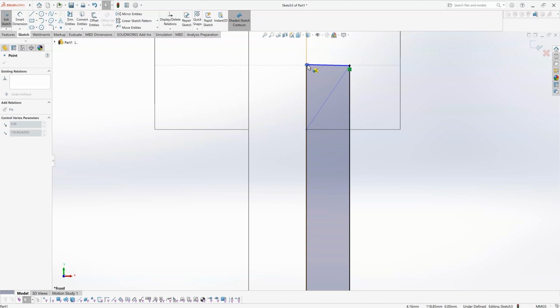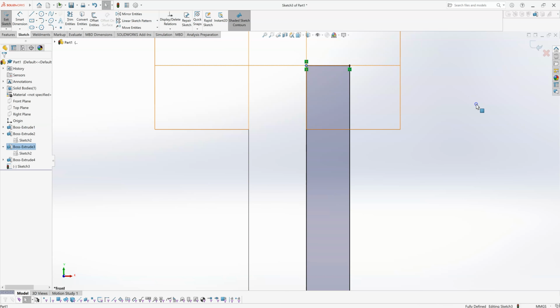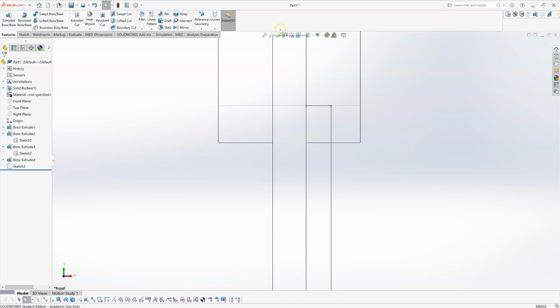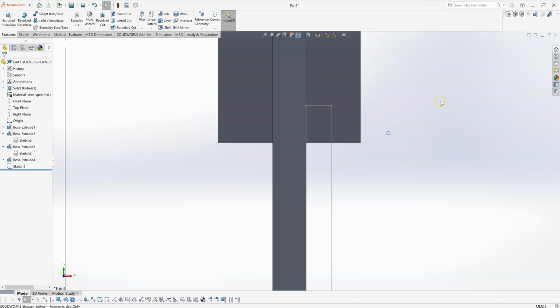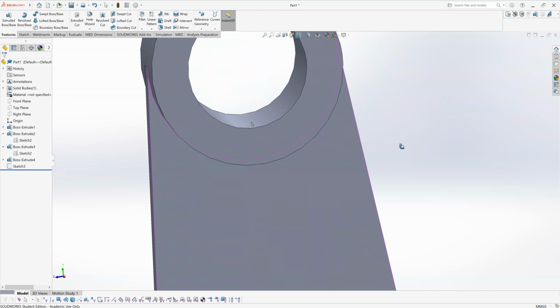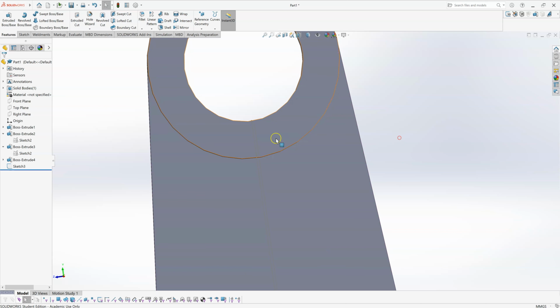And I'm going to drag that up and make it coincident with the inside of the hole up here. So that now is back fully defined again. Close out of my sketch. And we'll go back to the default display style here. So you can see the sketch there is going up now till it's just touching the inner surface of that hole there.